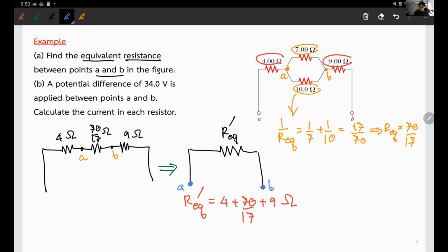Okay, so it's like you connect this 34 volt generator through A and B in the problem, and that leads you to calculation of your current flow simply by taking that 34 volts divided by R equivalent prime that you just calculated, and then you know what is going to be your current flow in the circuit. Okay, sounds all right enough to do the equivalent resistance calculation? Yeah, sounds good.